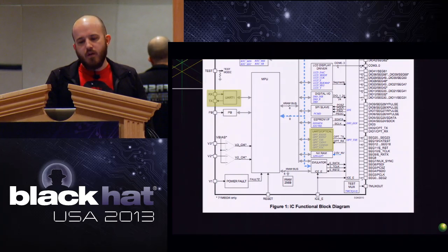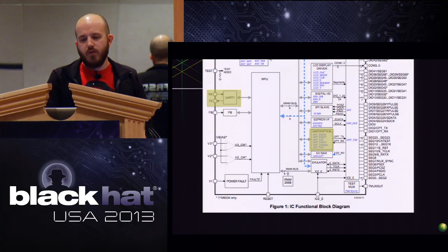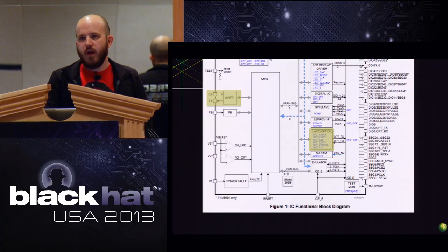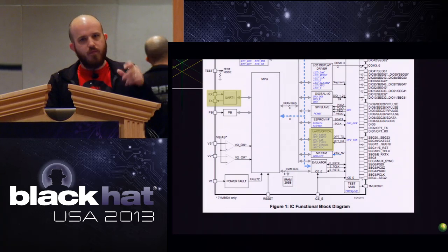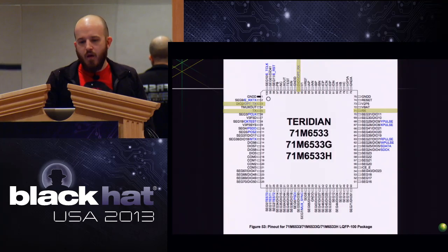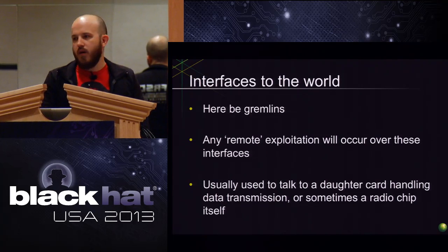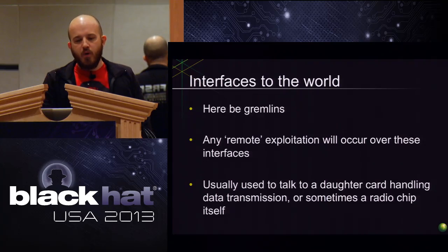All right, and then last case here, we'll talk about the interfaces into this guy. You've got a serial UART that's just kind of standard like you would think, and then it also has hardware that's designed to speak to an optical interface on the outside. That's the looking into the eye of the meter, like Cutaway's talk last year, where they match on the pinouts. These interfaces are where all your problems are, because this is where you actually get to interface with code. So remote exploitation occurs over these types of interfaces.